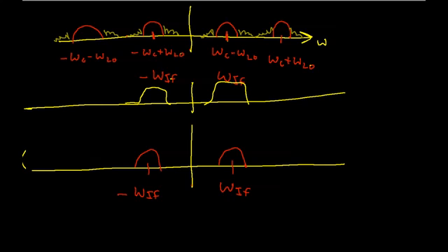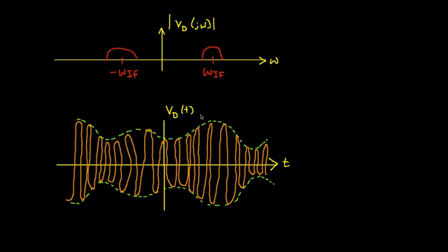Now I have only the signal I want at a particular frequency, and the only thing that is left for me to do is to reconstruct the signal, which is to take it from the intermediate frequency back to the original frequency band, and that original frequency band is oftentimes called baseband. So I've neatly redrawn the voltage input to the demodulator, which is the signal at the output of the bandpass filter, and I've called it V sub D. The demodulator will recover the original signal m(t) from V sub D.